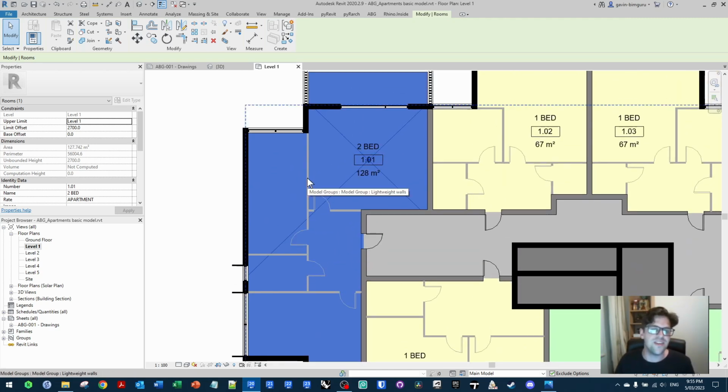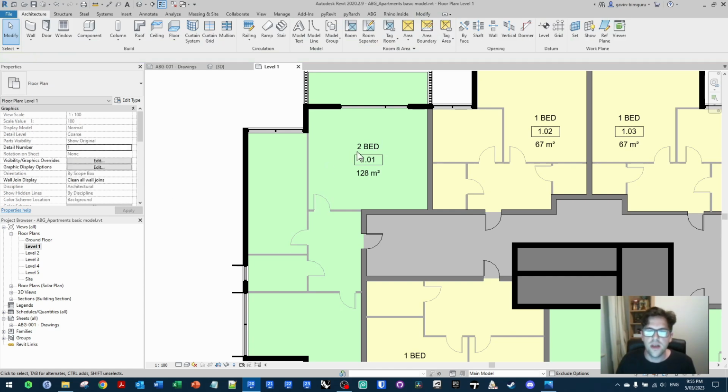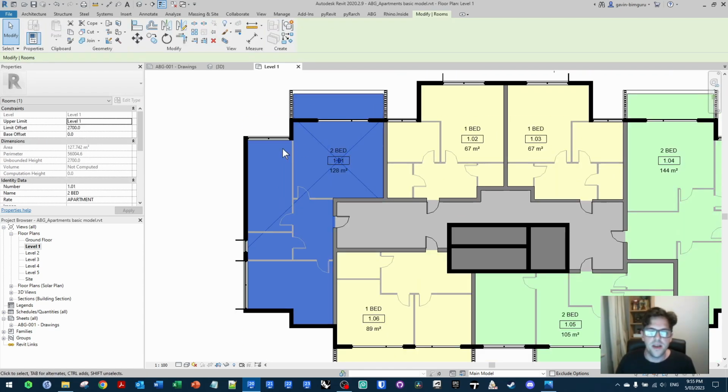This is going to make it easier for us to run a study, treating this room as one testing surface. I've done this by taking the internal walls and making sure they're set to non-room bounding, which is quite a common thing to do in firms when you're working with apartment buildings in earlier design stages, where you really just need the apartment to be a single object, and you might just be showing the internal walls for context, and you won't usually split these up into rooms until later.